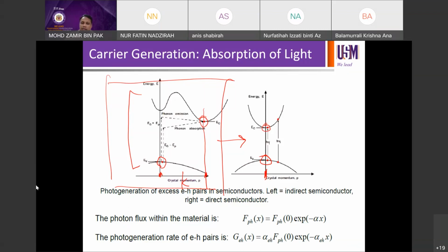So crystalline silicon has an indirect band gap, whereas amorphous silicon has a direct band gap. Okay, so if we talk about the properties on the left, then we're talking about crystalline silicon and germanium, but on the right we have quite a number of examples, like gallium arsenide, cadmium telluride, gallium nitride, amorphous silicon, and many more, right?